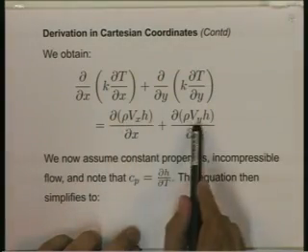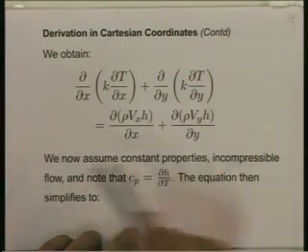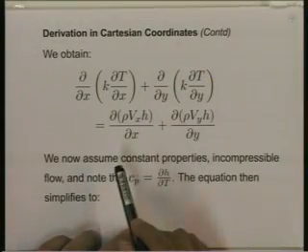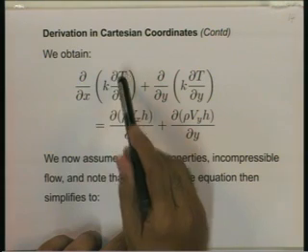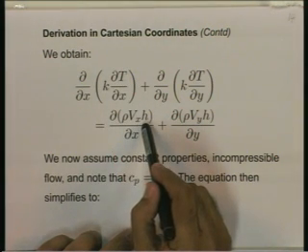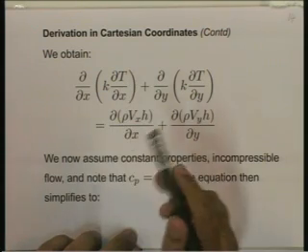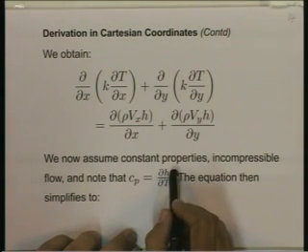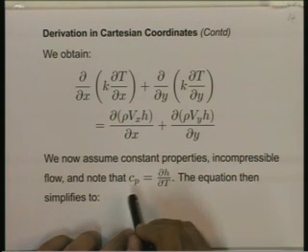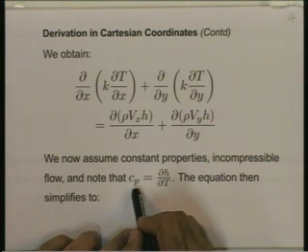You should immediately notice that if Vx and Vy are both 0, there is no fluid flow taking place, then what we have obtained is nothing but the conduction equation. The right hand side becomes 0. Now, although this is a proper energy equation, it is not directly useful because we have temperature and we have enthalpy. So we relate enthalpy to temperature by noticing that the derivative of enthalpy with temperature is defined as the property Cp, specific heat at constant pressure.